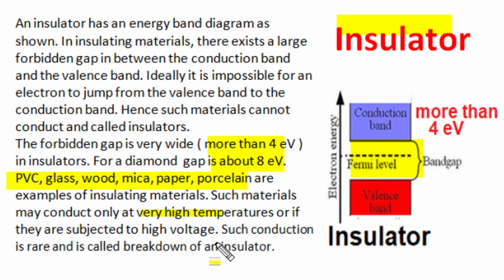Similarly, such material may conduct when subjected to a very high electric potential that establishes electric field strength more than the dielectric breakdown limit of insulator, and in that condition electrons of valence band will reach conduction band and material starts conducting, and that shows the breakdown or damage of insulating material. So we never apply high electric potential to surpass dielectric breakdown strength of insulating material, or use such material beyond a temperature of specified safe limit.